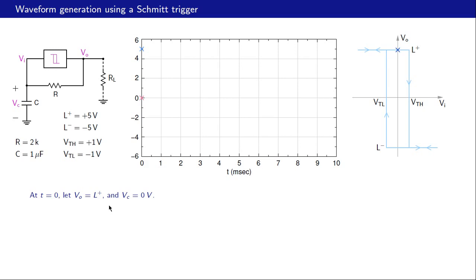Alright, so let us show this charging process. That is how the capacitor will charge. Since the time constant is 2 milliseconds, in about 5 time constants, that is 10 milliseconds, it would charge towards 5 volts. And the charging process would be almost completed. Now it doesn't quite reach there, and let us see why.